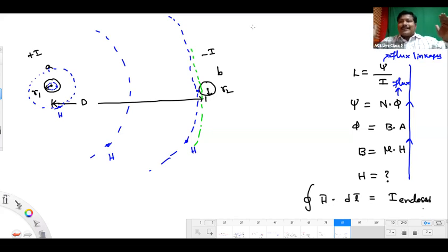If you are crossing that surface, conductor B current is cancelling conductor A current in the loop. So the resultant flux linkages are not the linkages produced by conductor A alone. Conductor B is also participating beyond that surface of conductor B. That's why we will take only up to the surface of conductor B. Yeah, all of you clear?